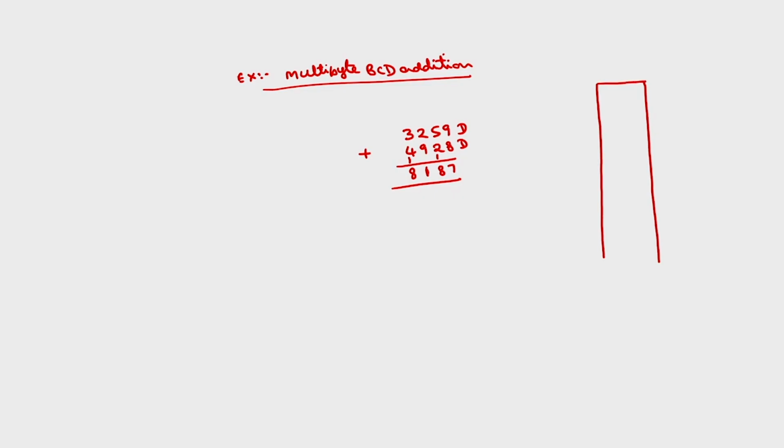Same data segment, with starting address 50000H, and ending address, if it is 64 kilobytes, 5FFFFH.